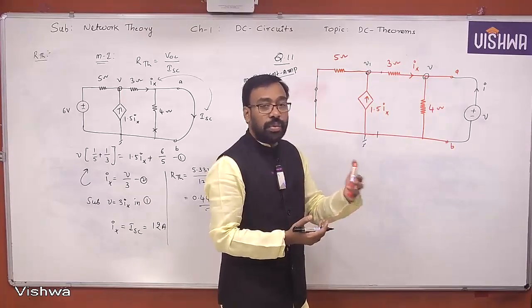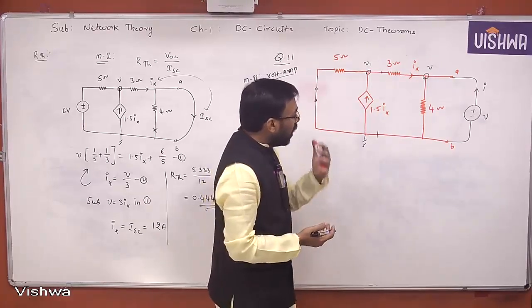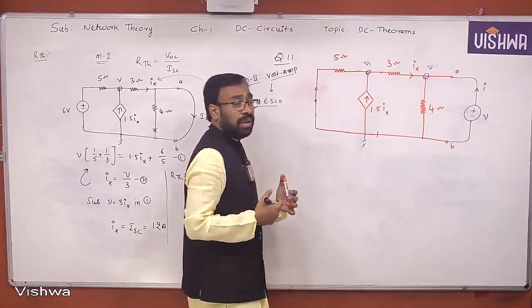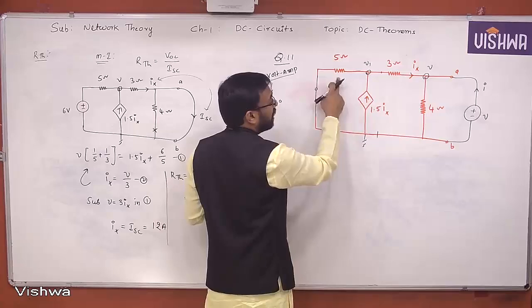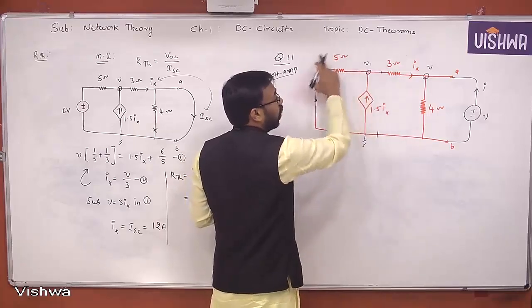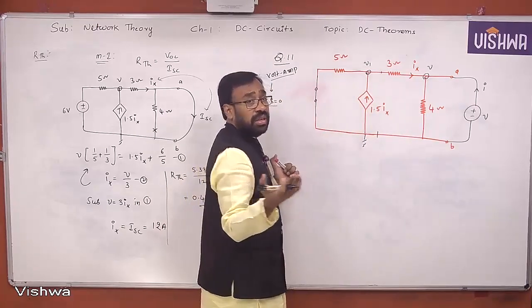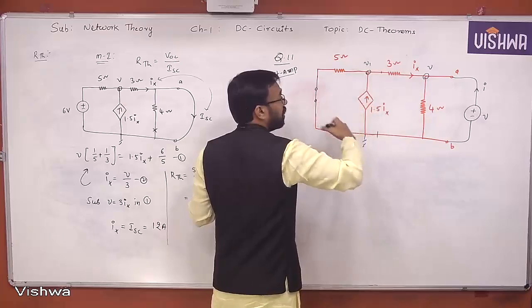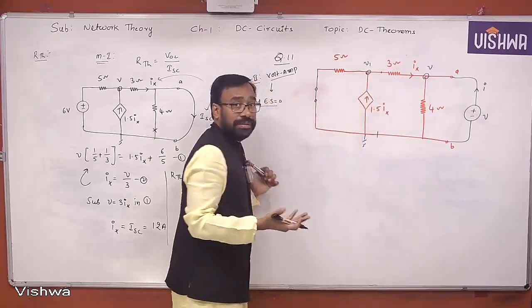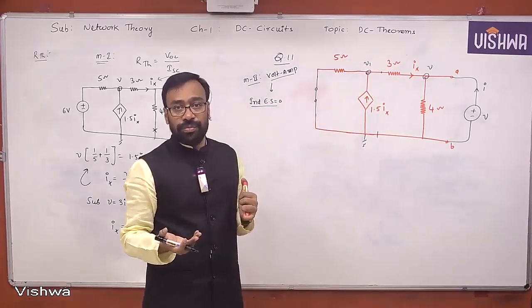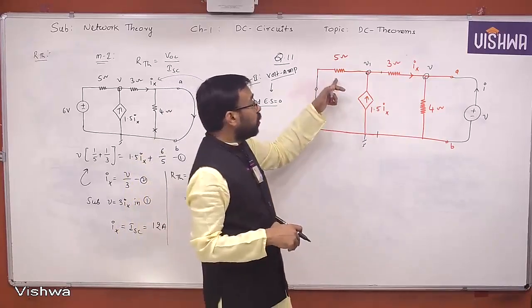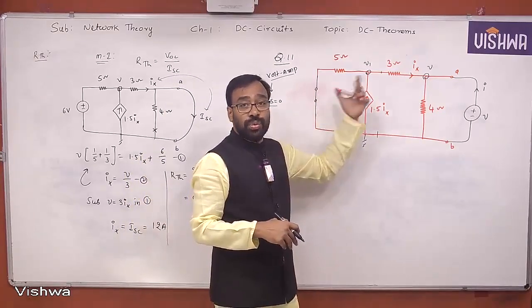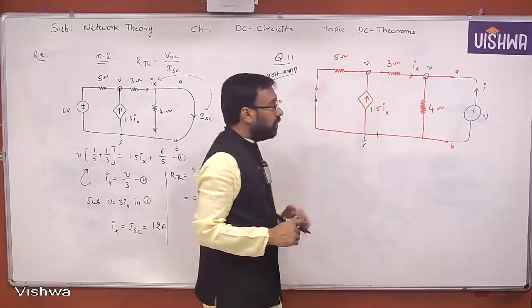Okay, becoming more complex. To avoid the calculation or to reduce the time, you got an opportunity here to convert this current source with a parallel resistor. Can be converted to what? A voltage source with a series resistor. When you convert, all these elements will become in series, then V1 can be eliminated easily. Yes or no? V1 can be eliminated. There is no need to take the V1 variable once you convert these, okay? Yes or no? Okay, we'll do that.